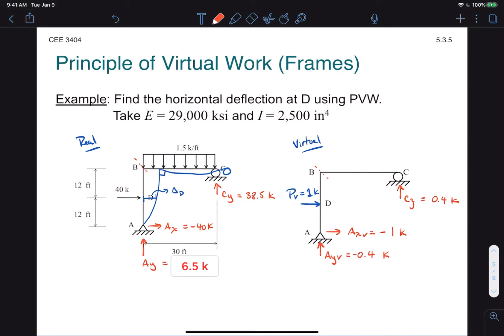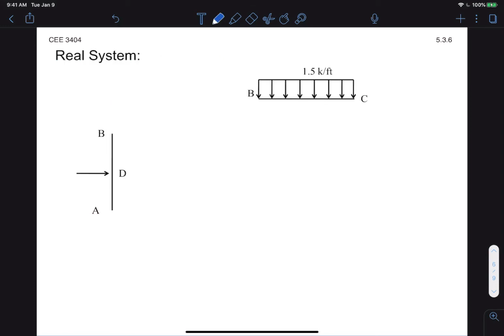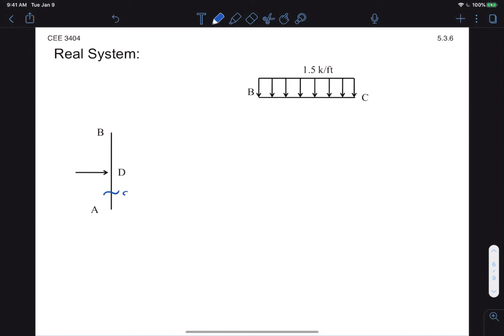And then we'll also need to split it into sections of continuous loading. So first we split it into 2 beams, and then we notice that we'll need 3 sections here. A section 1 before the point load, a section 2 after the point load on AB, and then just one for beam BC, which we'll call section 3.